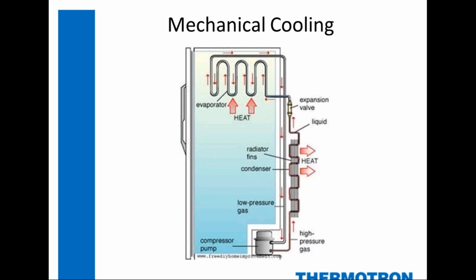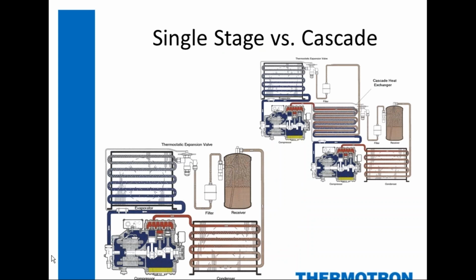And perhaps you've even heard of the first law of thermodynamics that I learned about in school, that you can't create or destroy energy. You can just move it or change its phase. And that's really what's going on here with a mechanically cooled environmental chamber, or in this case, a refrigerator. So down here in the left corner is a graphic of what I just showed you, a simple one compressor system, and this is what we call a single stage refrigeration system. And with the correct refrigerant, this will get you down to about -40.